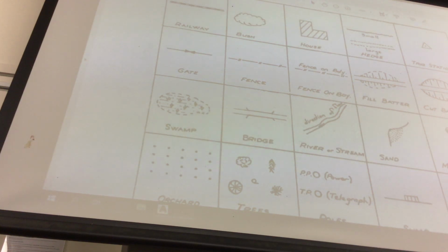The reason is that this file came from a 3D file originally, and I flattened it, and it might look in plan view like they're touching, but they might well be quite a bit apart. And because of that, it's the old Al Capone theory going on, the hatching will escape given a small hole, okay? So I would personally just go P-line, dunk, dunk, dunk, dunk, dunk. It doesn't have to be that accurate, as long as it's fairly close, and then you can click on the P-line to form your hatch.